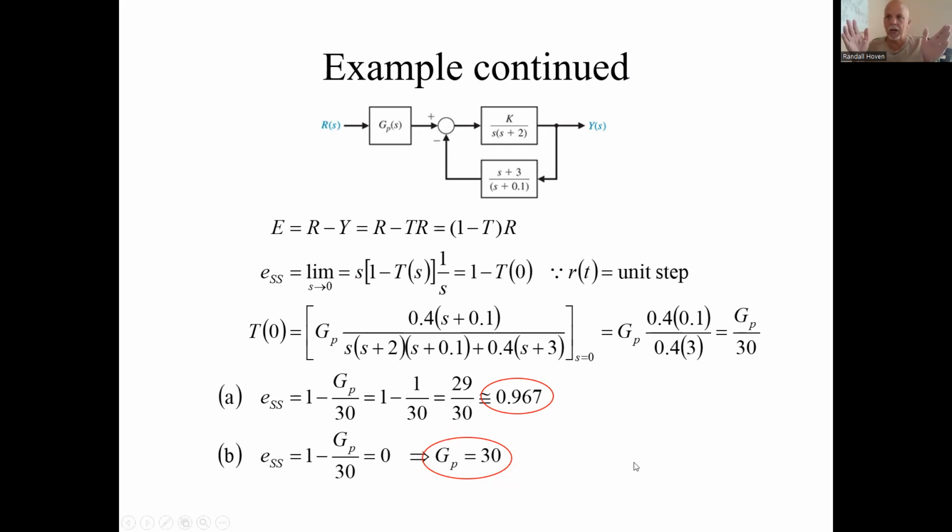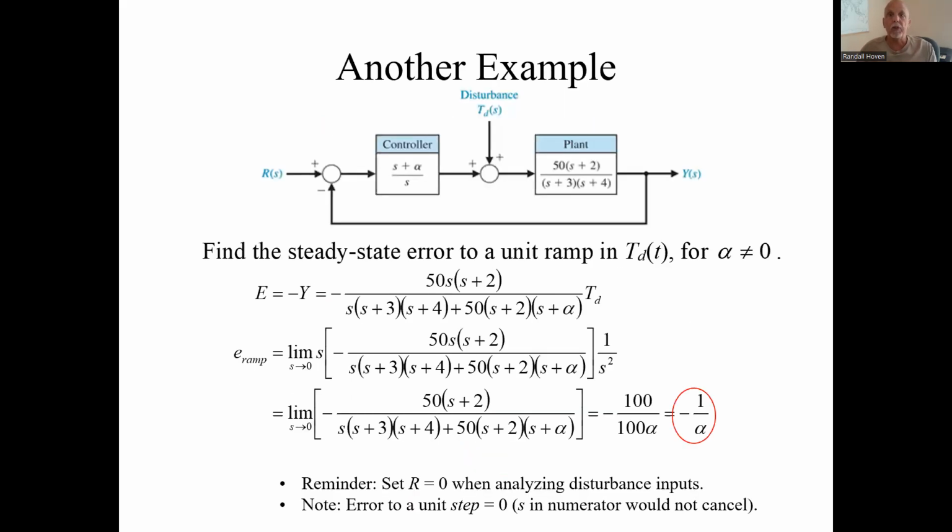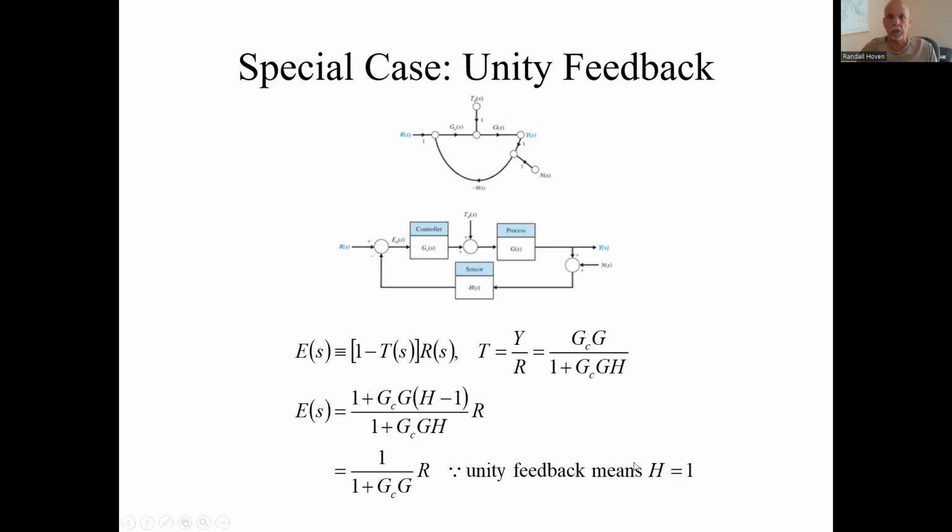But anyway, the overall process is to find an expression for the error in the Laplace domain, and then apply the final value theorem for the type of input you were asked about. Here's a case, I might be running long, but I think it's the only other one.